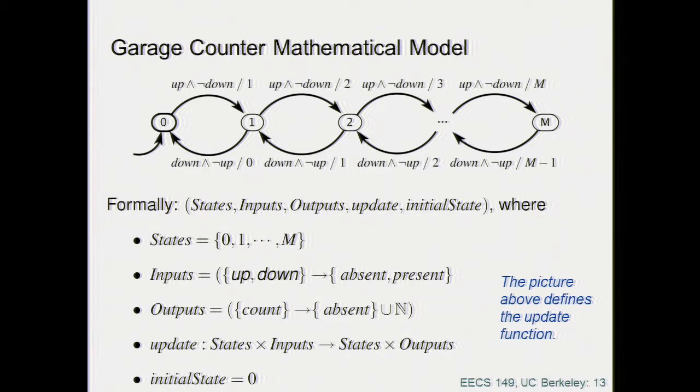Other times, okay, this is the value, and then chunk, I go down to 0, and it's another value, boom, and I go down to 0. This is not sample and hold. And there are two different circuits that do the same thing. So they are both D to A converters, but they operate in a different way. So in general, the most used model is sample and hold. So you keep the value there, right?